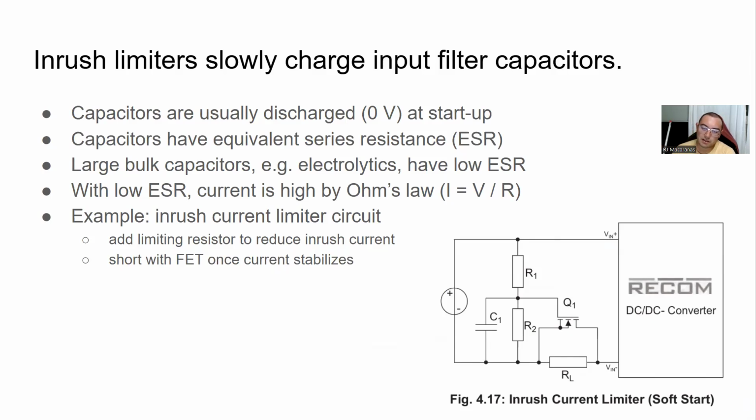Because the current is inversely proportional to how much resistance there is. And so we actually need a way to limit this inrush current due to all these capacitors.